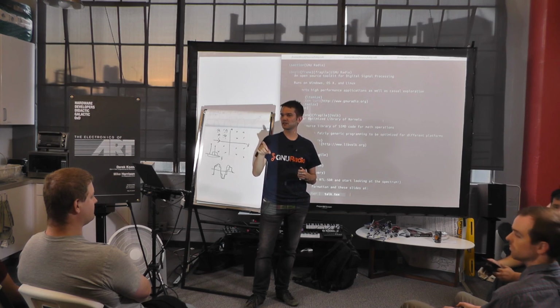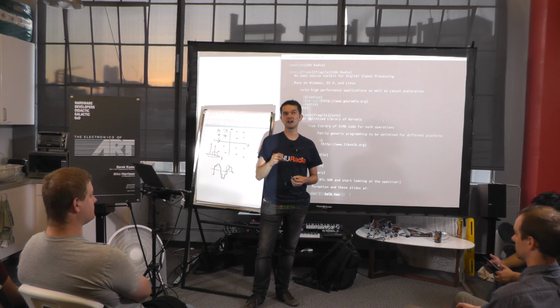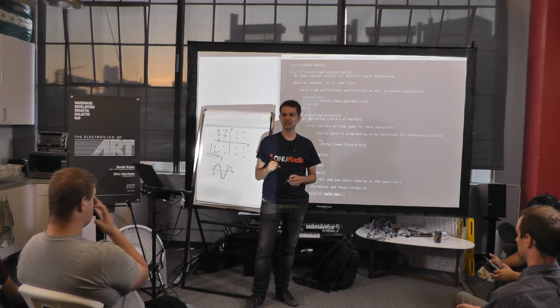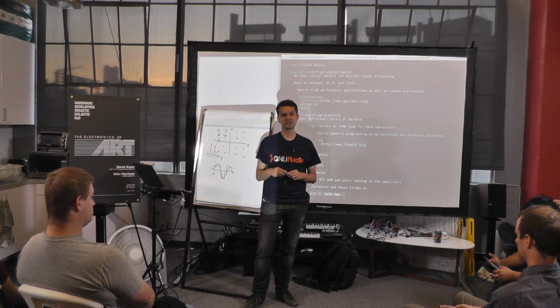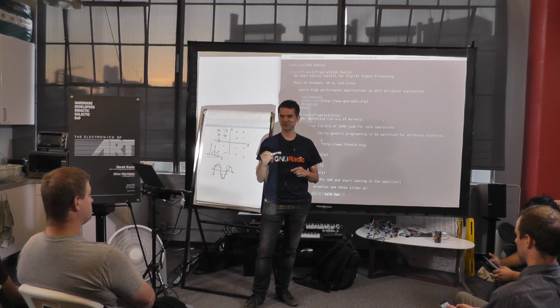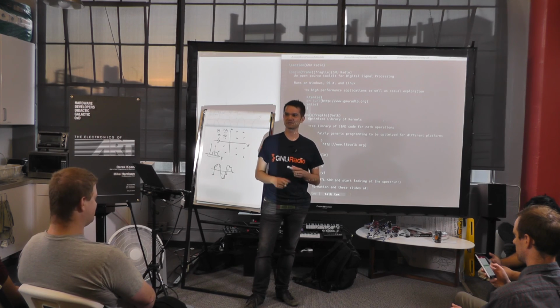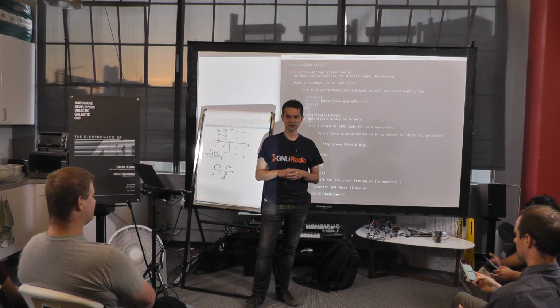Any other questions? Can you receive Iridium signals on cheap hardware? Yes. I forget what frequency Iridium is at, but I think so. And there was a talk at the Chaos Communications Congress a year ago where they actually figured out how to demodulate the Iridium signals, and it turns out they're not encrypted. And there's now support for that in GNU Radio. So you can drag and drop the gr-iridium block, and it will demodulate it and drop out audio files for you.